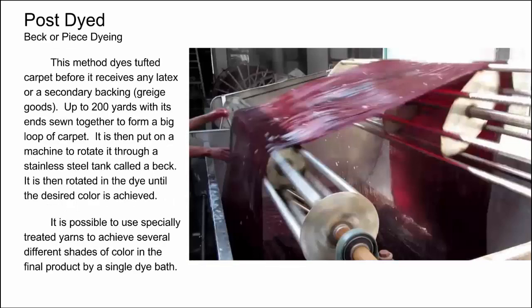Now we're going to cover some of the post-dyeing techniques. So we're dyeing the gray goods in these dyeing methods. First is Beck or piece dyeing. So in this method, we're dyeing the gray goods. The yarn is already stitched into the secondary backing, and we're going to dye the whole thing. Basically stitching up to 200 yards of carpet. So we're going to sew the ends together to form a big loop of carpet, and then we're going to run it through this machine.